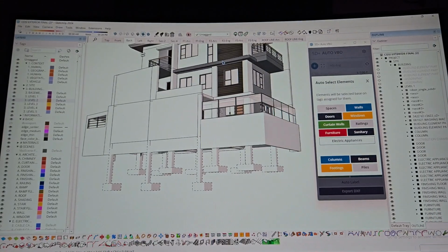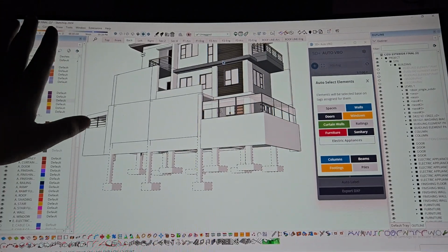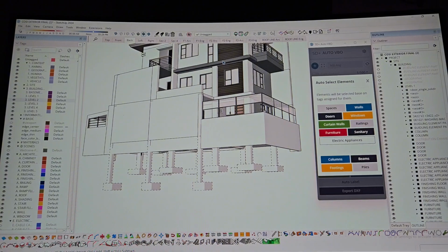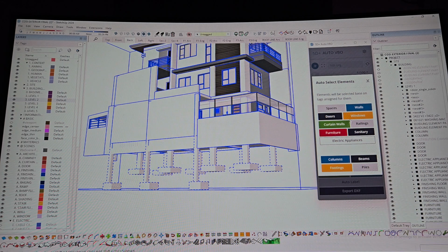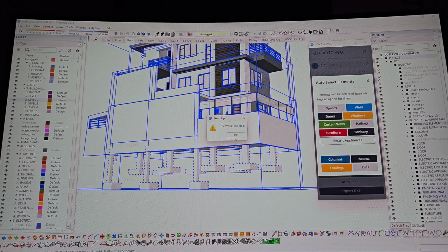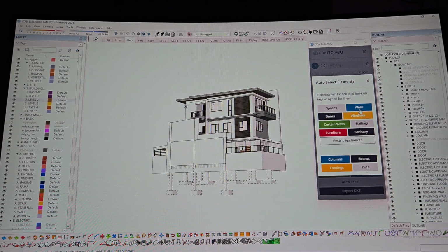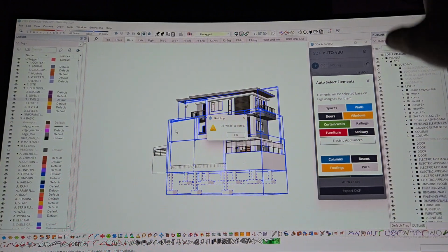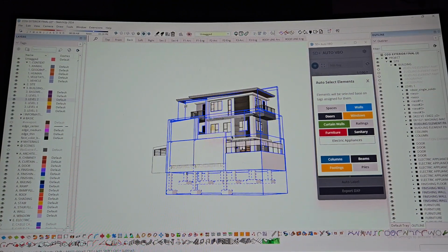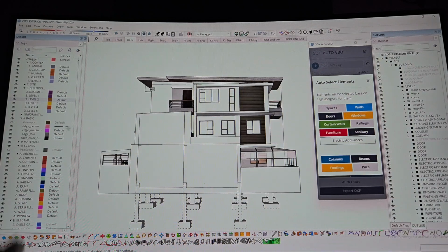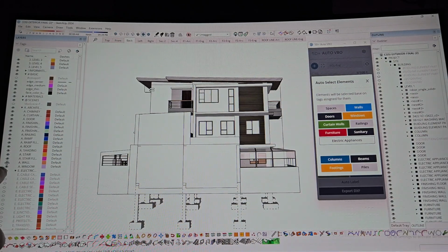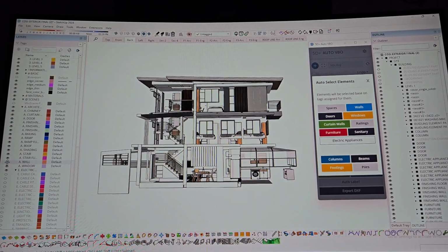To work as BIM, just familiarize yourself with layers or tags I put on my left side, outliner I put on my right side, and entity info. For example, if I would like to select all my walls, I can use the VBO extension, or I can go towards my outliner and hide them as well, like that. Okay, or I can go to my left side and select wall because I tagged them properly.